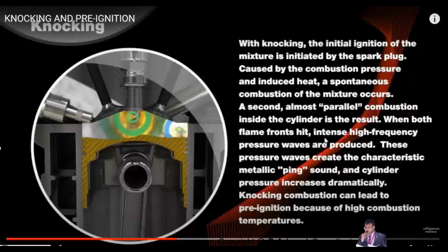When both the flame fronts hit, intense high frequency pressure waves are produced. The output is a sound. These pressure waves create the characteristic metallic ping sound, and the cylinder pressure increases dramatically.